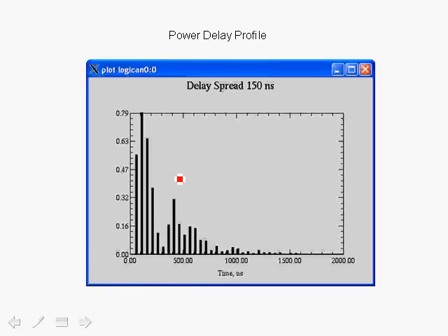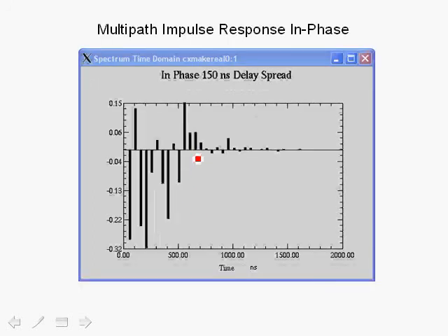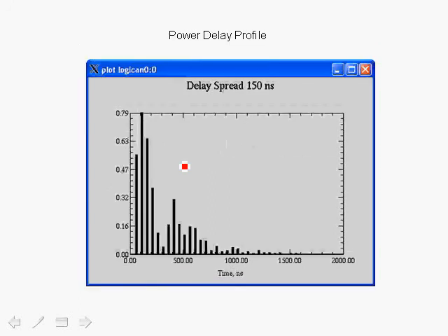In order to model multipath delay spread in software, then, we would pick the impulses from a normal distribution, but we will ensure that the actual delay profile follows an exponential decay to model the actual environment you would encounter in an indoor wireless environment.